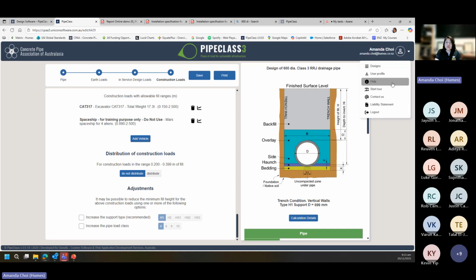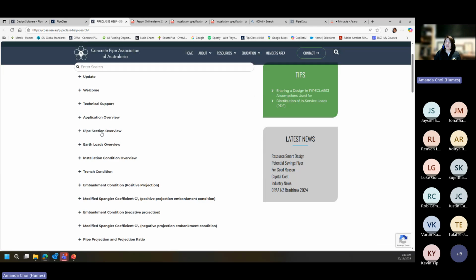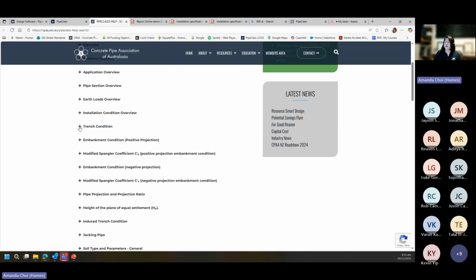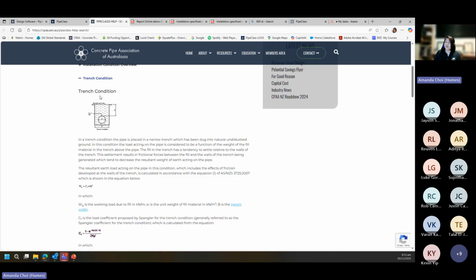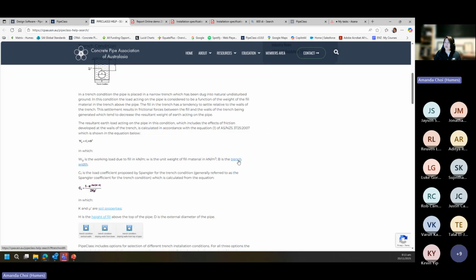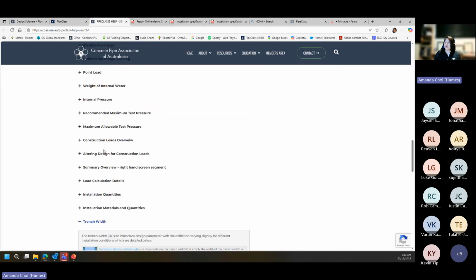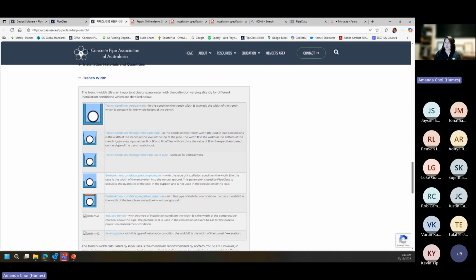This one is quite useful, especially as I imagine you won't remember everything I say today, and you may have a specific thing that you are looking for. If you click on that, it goes to the help page. It has all the topics that you may want to look at. For example, if I'm looking for the current strain condition, it will explain what the strain condition is, and even the equation and also the standard it is referring to. And if you want to know about trench width, you can click on that and it will go straight to the trench width topic as well. So these are very helpful if you get stuck on anything when you're using PipeClass3.